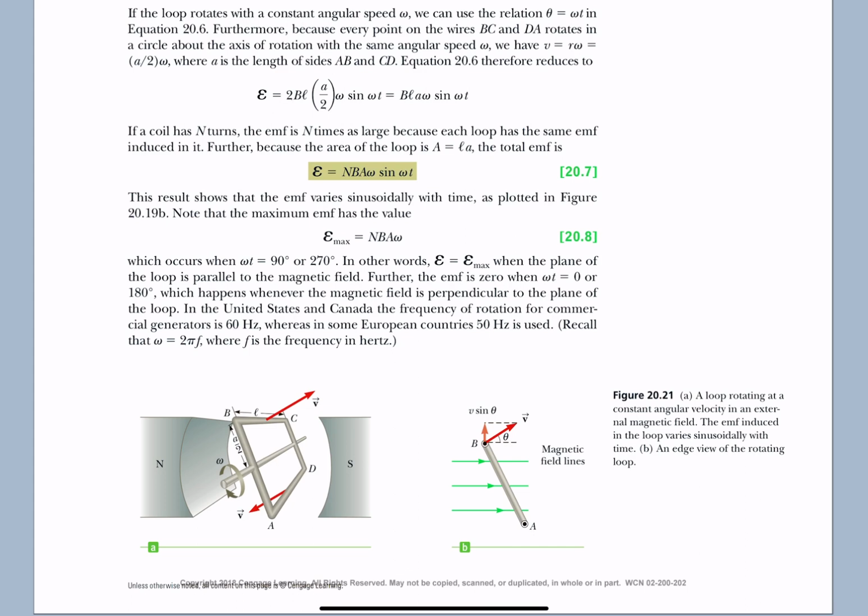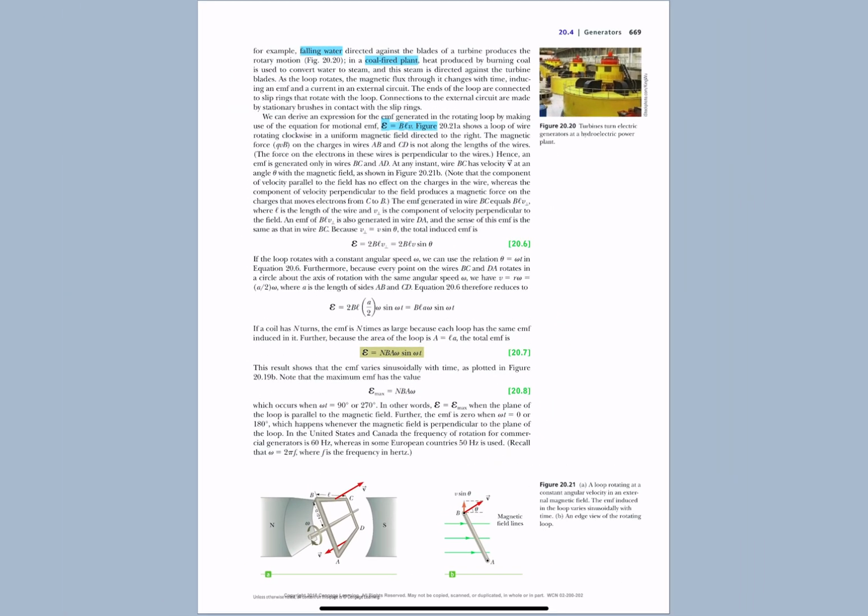But once you reach the top where the picture shows it, once your length from point B to point C starts to move parallel with the green flux lines, then your induced voltage goes to zero. Fortunately, the momentum of your spinning solenoid carries it past so it can begin to go down the other side and you continue to induce voltage.